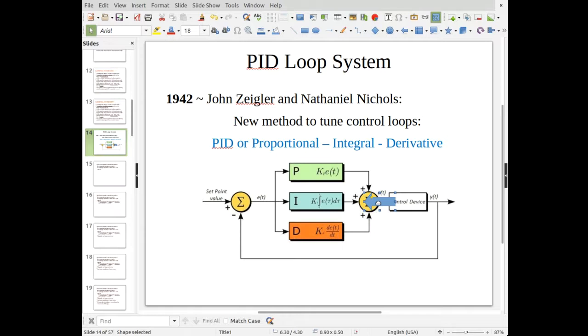And so we can't really do it. If you do a closed loop control, you can't drive it all the way up to 10 volts. So we end up driving it to 2 volts instead of 10 volts so that our system can actually do it. All right. But the point of the integrator is it will remember the error and it will respond